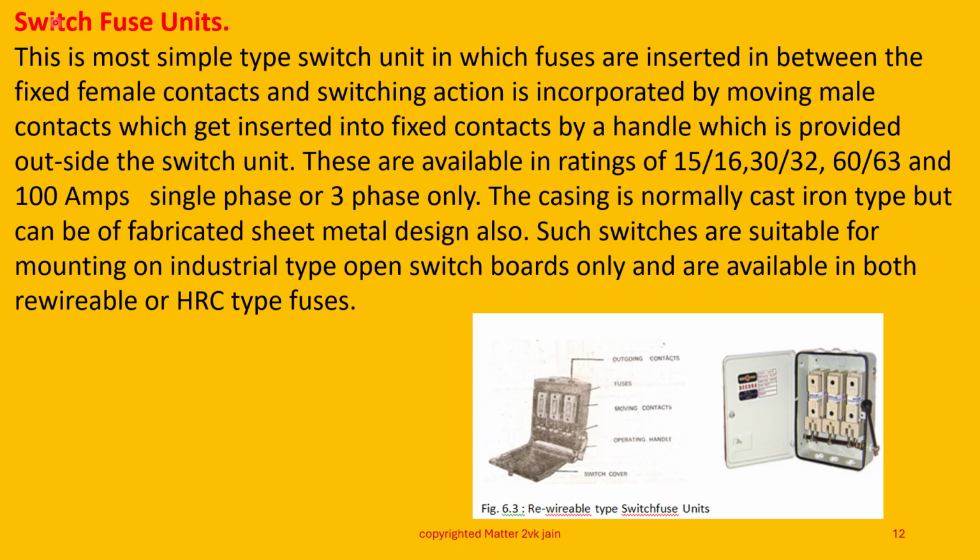Friends, switch fuse units were deployed heavily about 30 years ago. This is the most simple type of switch fuse unit in which fuses are inserted in between the fixed female contacts, and switching action is incorporated by moving male contacts which can get inserted into fixed contacts by a handle which is provided outside the switch unit.